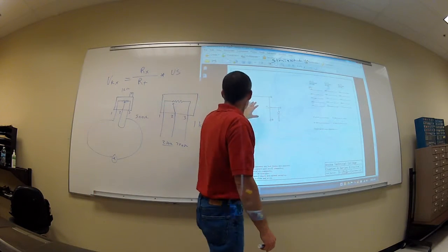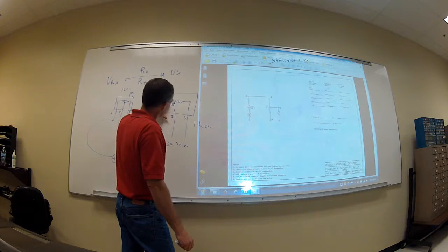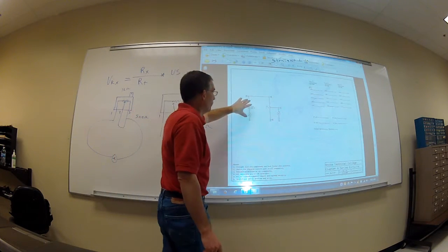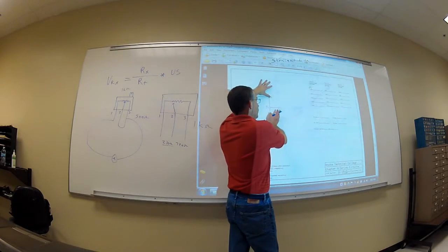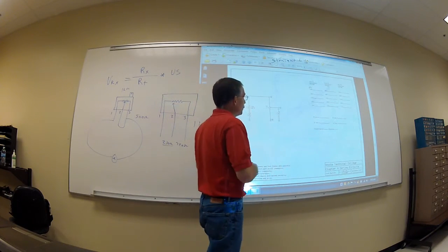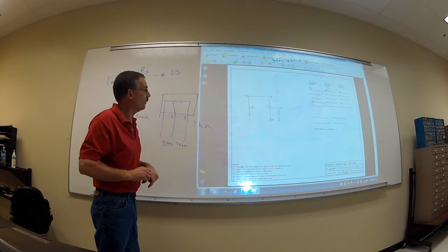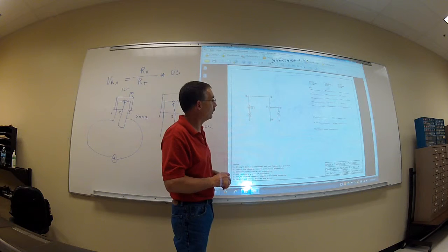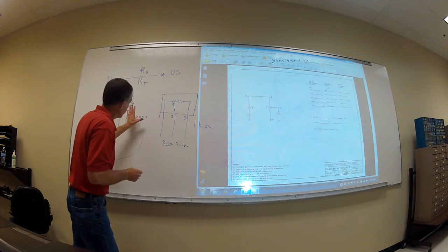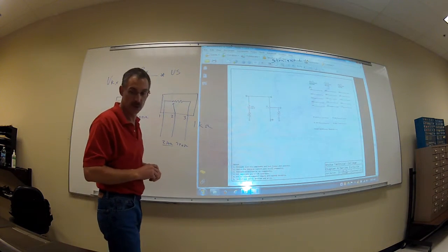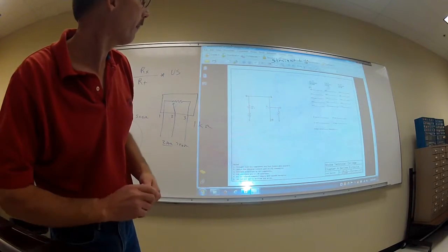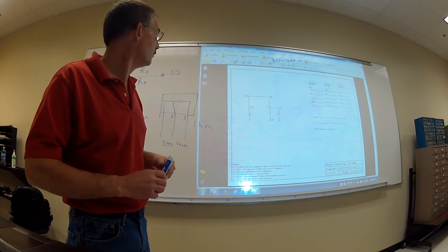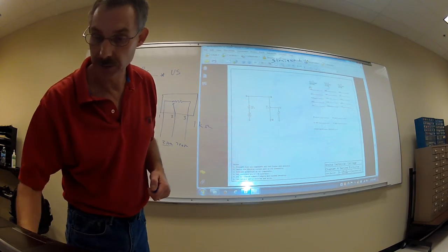This one here we're using as a rheostat to give us a variable resistor. We're going to be looking at it more as a potentiometer, looking at different voltages and stuff like that. That's how we use them for controls. So we're really going to be focusing on how we use them as potentiometers, not so much as rheostats like we've been seeing in the circuits. We use them both ways all the time, but potentiometers we use a lot for speed controls and different kinds of controls.